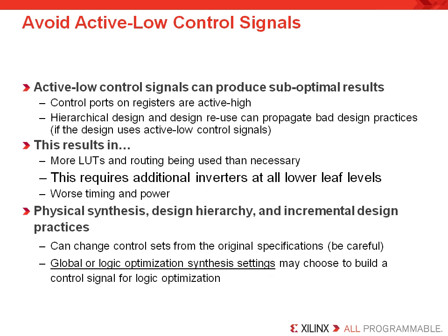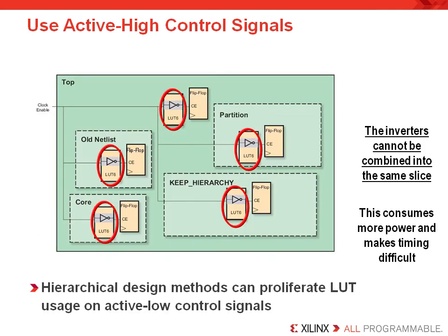If you use any hierarchical design techniques, meaning you are using partitions or maintaining hierarchy, instantiating cores, using multiple netlists, and then using bottom-up synthesis, be aware that it can increase the number of control signals in your design because the flip-flops do not have a programmable inverter. With hierarchical design practices, each signal would have a different name, and you would still have to run each signal through an inverter, which means you're burning a LUT input or even a whole LUT.